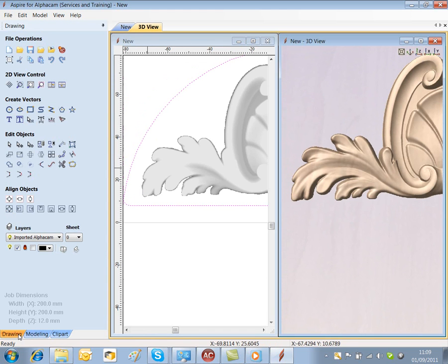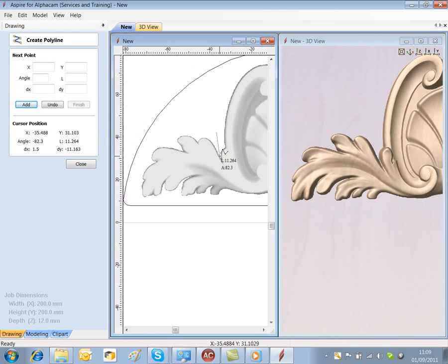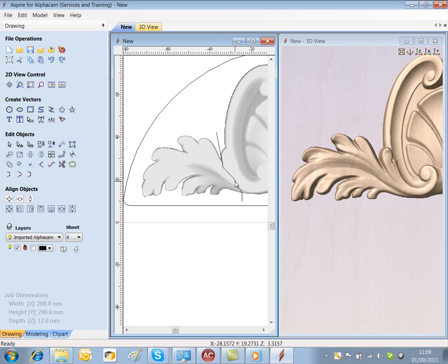So going into the drawing, I select this draw polyline, bringing that down almost vertical into this little gully here, and then coming round across here and then down. Escape out of that. Select it, then press N, which gives me the nodes.